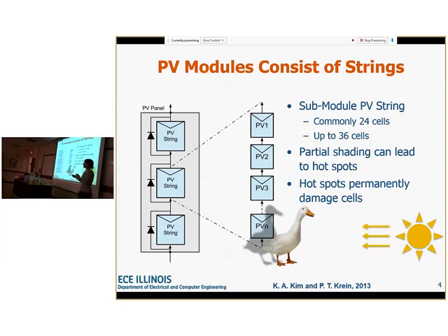And we'll look at the IV curves in a second, but it starts to act like a load, and it actually heats up. So it doesn't actually turn red, but it heats up. And if this heats up for long enough and at a high enough level, you can start to form a hot spot and actually begin to degrade the cell.